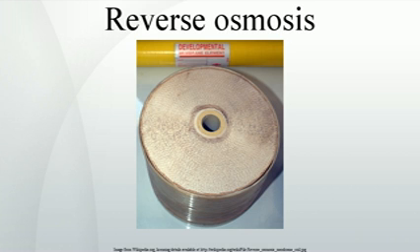Reverse osmosis process for water purification does not require thermal energy. Flow through reverse osmosis systems can be regulated by high-pressure pumps. The recovery of purified water depends upon various factors, including membrane sizes, membrane pore size, temperature, operating pressure, and membrane surface area. In 2002, Singapore announced that a process named NEWater would be a significant part of its future water plans. It involves using reverse osmosis to treat domestic wastewater before discharging the NEWater back into the reservoirs.